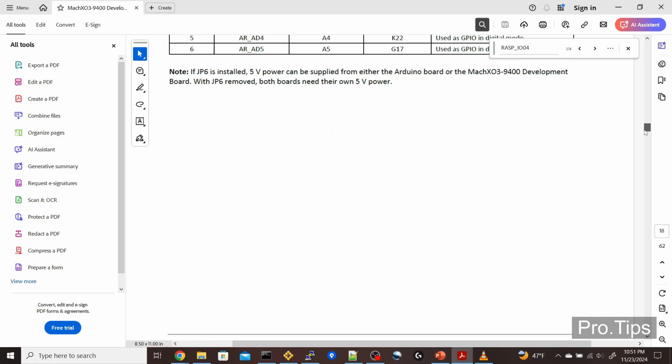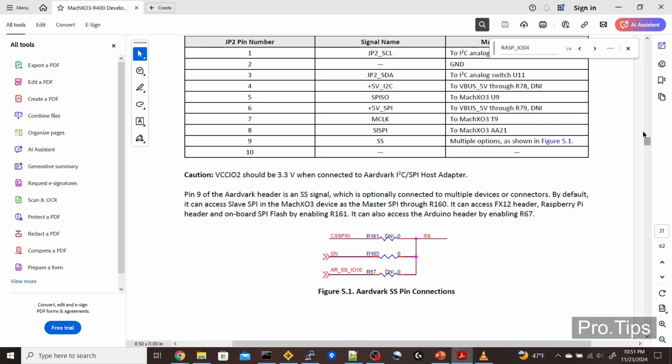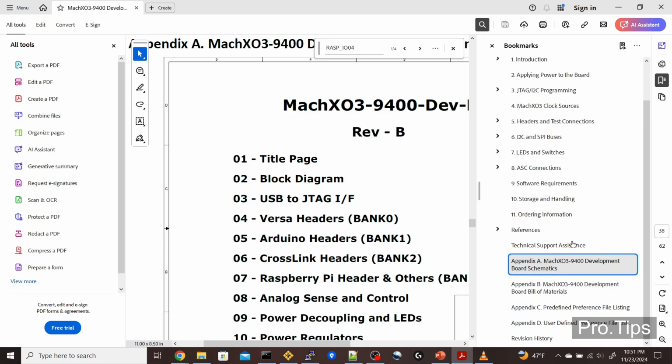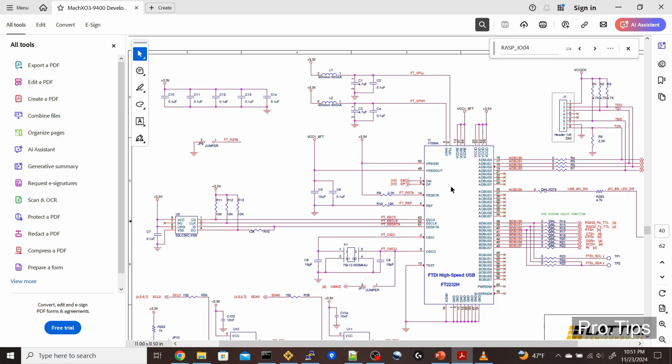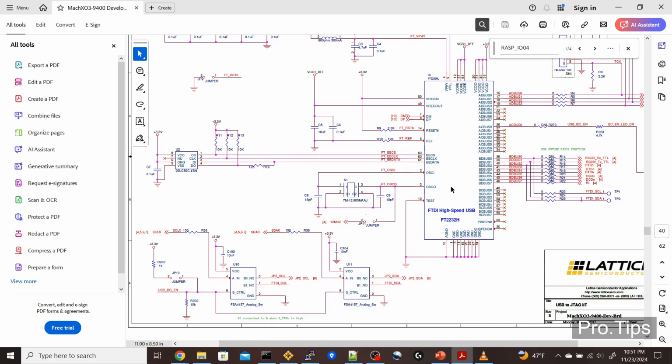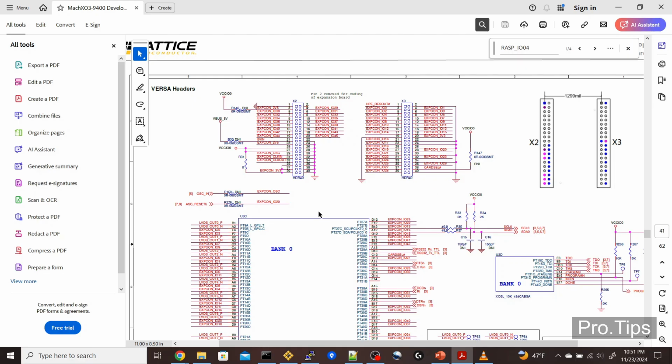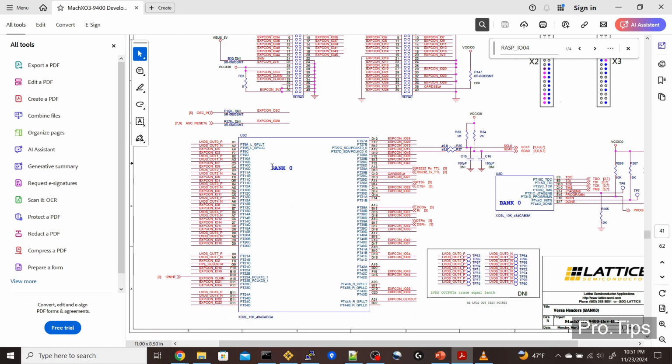If we go down below, we can click on the block diagram bookmark here as well. You start seeing various IOs that are available on the FPGA on different banks. The one that we care about is PCLKT. Those are the primary clock pins, right? So we want to see which one is available. B12, A12 are not available. The 12 megahertz one here is not available as well.